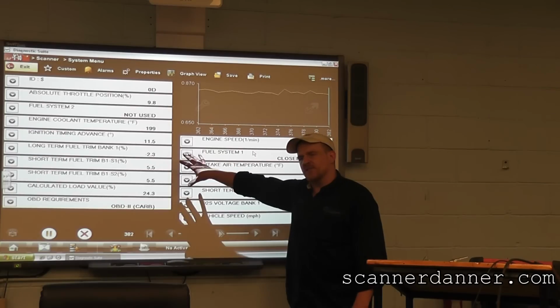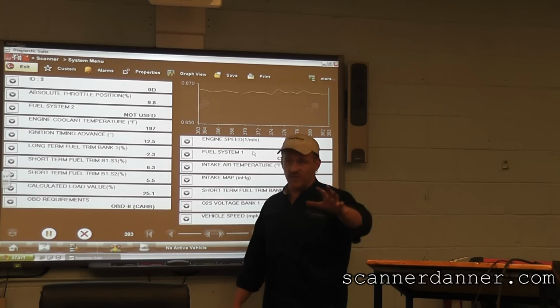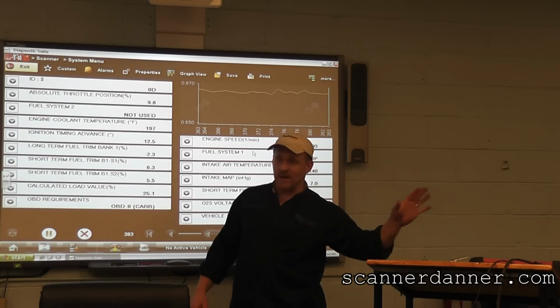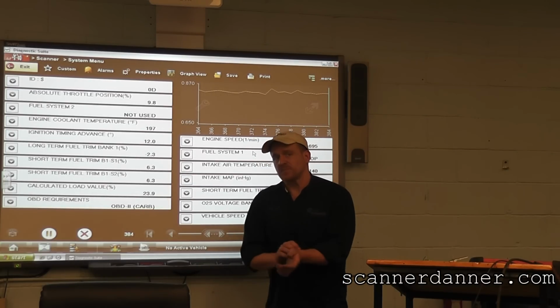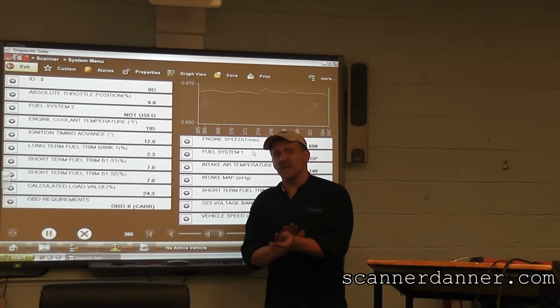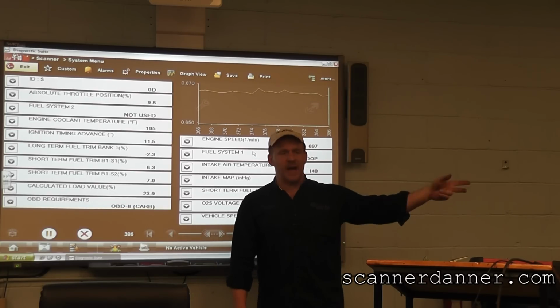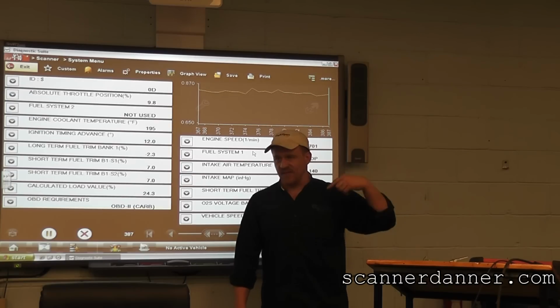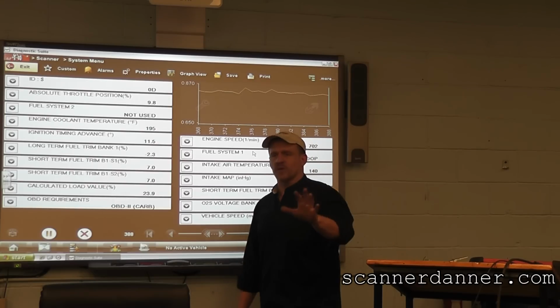We'll exit out of this mode and see if we can clear the data through the factory mode. We'll see if we can do that. If not, I'm not disconnecting the battery. I don't care. We have one more piece. We have a check engine light on that we didn't have before. So I want to look at that light real quick. And it could just be because I had the TPS and MAP unplugged that I set those fault codes, and we did have the key on, and that's my guess, that those codes would just wipe out and be done.